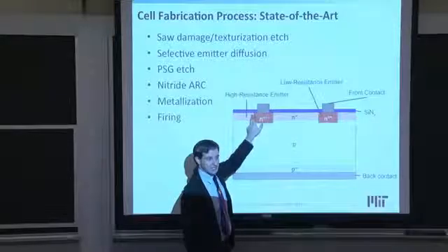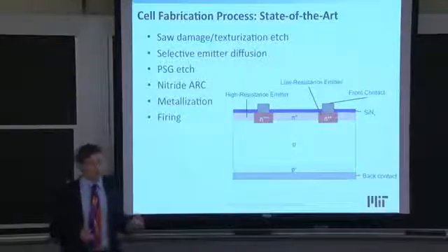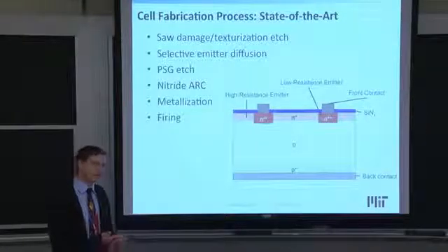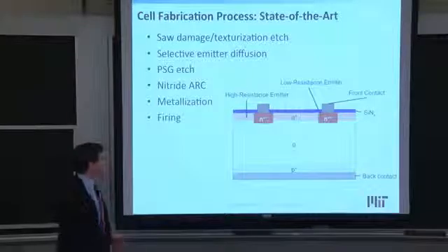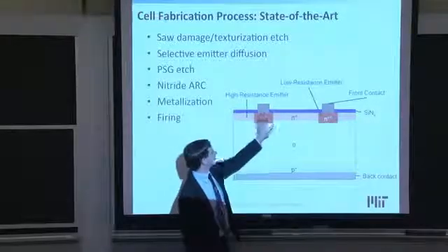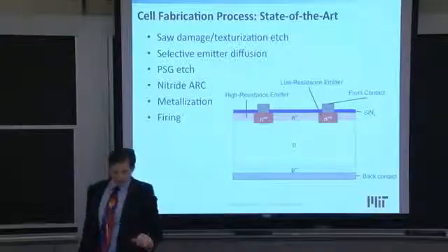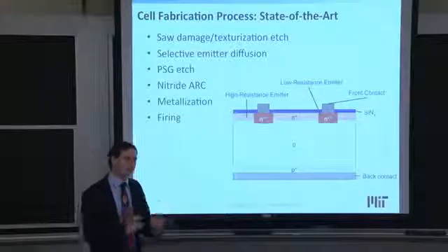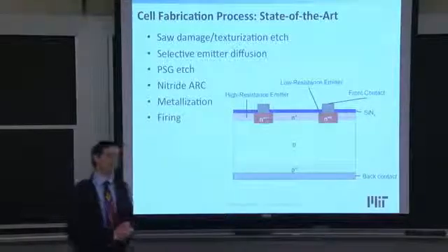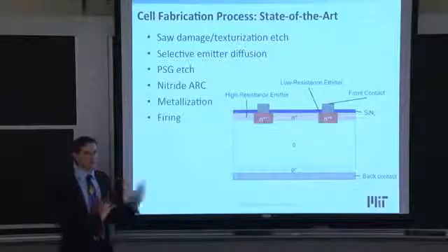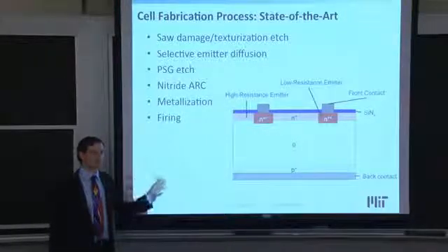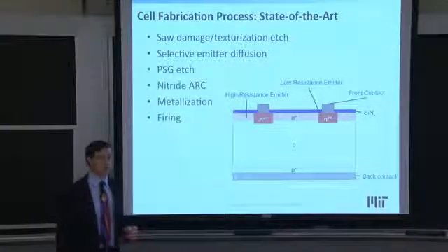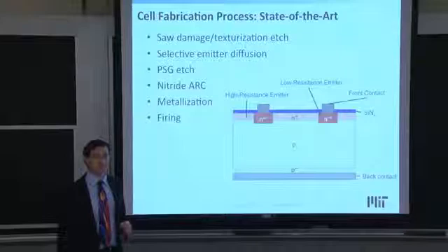This is only 70 nanometers thick, but silicon nitride is a very strong material. It's a ceramic material, so you have to be able to etch through the silicon nitride and make electrical contact with the silicon underneath. And some of the earliest screen-printed metallization cells that got in the range of 15 or 16% efficiency only made electrical contact in about 10% of the silicon. But it was enough to have these percolation paths for current to flow up into the metallization. It's a miracle that it works at all, but it's a very effective, cheap manufacturing process that nevertheless is still being used in commercial production today, even among some of the highest efficiency cell architectures.